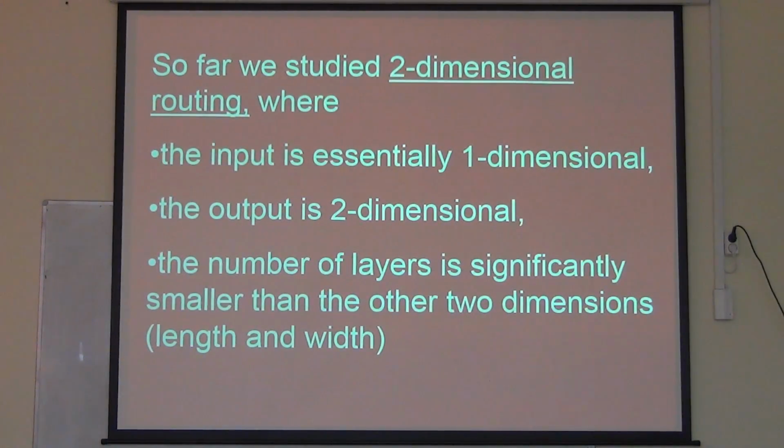I didn't speak about switchbox routing, which is obviously more difficult than channel routing. It contains channel routing as a special case. And all these problems are really hard. So typically a 20 by 20 size switchbox, whether it can be routed on 4 layers or something like that, is hopelessly difficult even now. There is no really good solution for that. Not only are they NP hard, but as far as I know, there is no really effective solution for that.